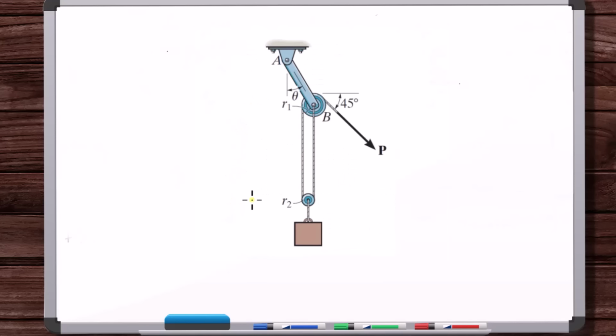Okay, so in that case, you can take a snapshot at any point in time of the pulley rope system and do a free body diagram, right? Because you can think about the rope and the pulley together as rigid. You could do whatever you want. You could make just a cut here, a cut both places, and take all of this out into empty space. Maybe you could make a cut here and take all of this, unpin it here and take all of that. Make a cut here and unpin the roller here and take all that out. Do the pin here and take all this out, however you want to do it.